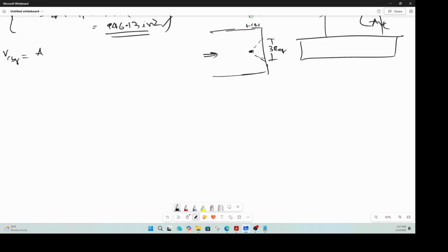VCBG, again, same formula: AVC by AVCO times CED,V, the edge distance related modification, CEC,V, the eccentricity related modification, CC,V, the cracked concrete related modification, CH,V, your shallow embedment related modification, times your VB.